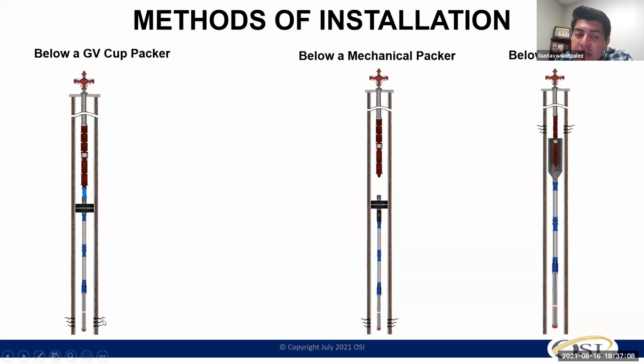So the right measurement is actually being able to produce a portion of the sand. Let's put everything in numbers: instead of getting, let's say, 300 pounds at the same time, you maybe are getting just 5 pounds of sand with every barrel that you're producing per minute, or less than that. So you cannot disappear the sand. The only thing you're doing is delaying that process, regulating, and providing the right amount of sand that goes through your pump. But normally you go with your ESP and it's exposed. It doesn't have any sand control underneath it.